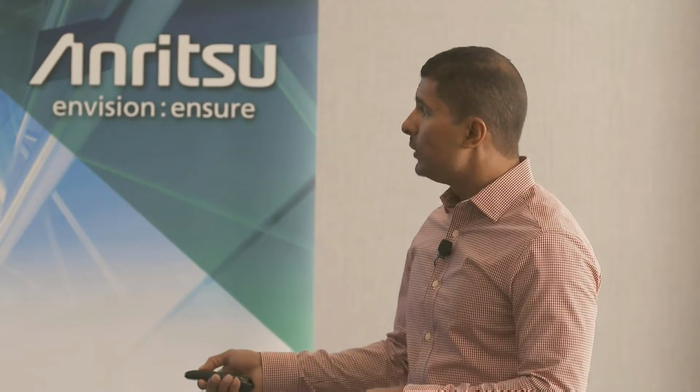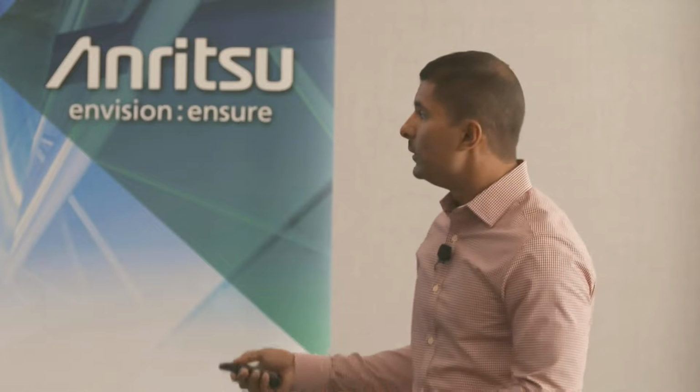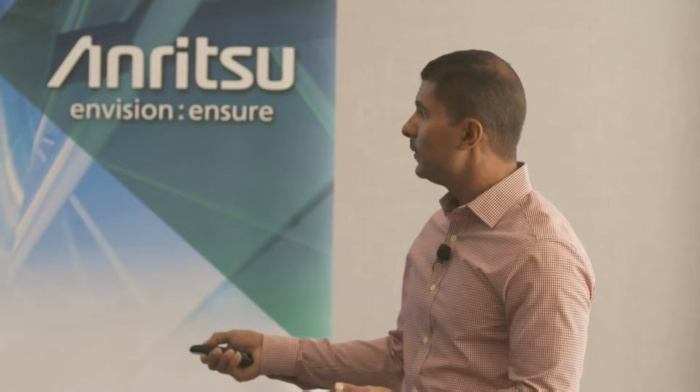So what you'll see on the bottom here is that 3GPP created what's called splitting the Ethernet, or functional splitting. So here's the fundamental premise behind radio over Ethernet, or eCPRI. We're taking the traditional CPRI that we talked about in the previous slide and turning it into packets, Ethernet-based packets. Not only are we turning it into packets, but depending on which type of split we choose, or how much data we want to include or not include in that packet, will determine where that RF data is being terminated.